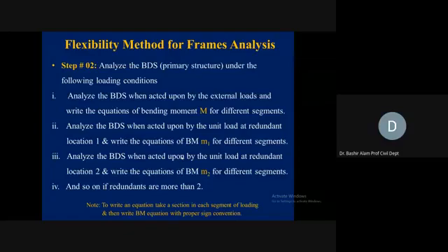This is the same as what you did in the 4th semester for finding the displacements at various points in the case of frames. You have already discussed the virtual work method. At the point of interest where you are investigating the deflection, we apply a virtual load of unit intensity. This is the same thing.